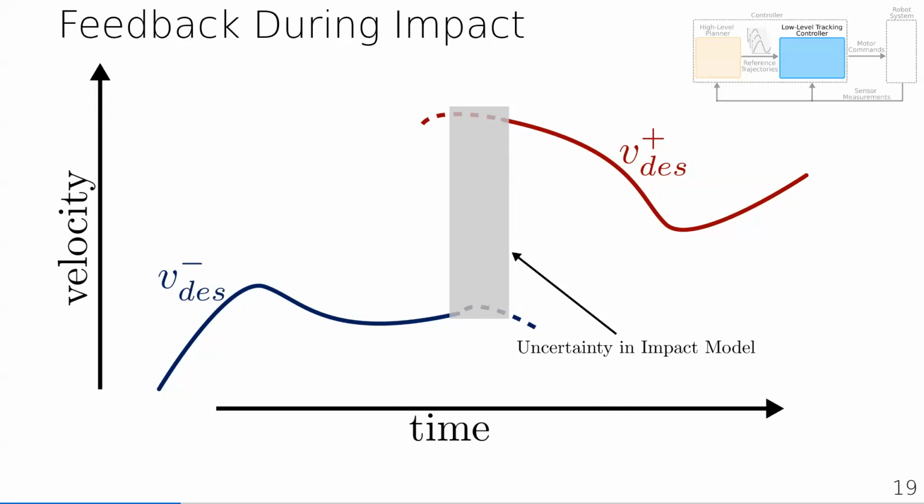There's been a lot of interesting work a while ago on more compliant actuators, like series elastic actuators. They dampen the impacts. Cassie actually has some of those springs. In practice, I think the field has moved away from actual mechanical compliance just because it's so hard to control. These add additional degrees of freedom you can't actually control. The field has moved in favor of more direct drive actuators, where they do experience impacts really quickly and fake your compliance in a way. So I think yes, you could dampen out the impacts a bit, but I don't know if that's the direction the field's going in terms of mechanical design.